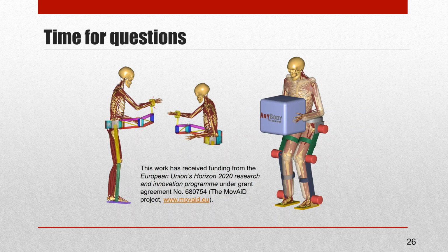Okay, thanks. So let's go to the next question. How do we calculate the total metabolic power? The current versions of AnyBody have an opportunity to calculate the metabolism of every muscle. Whenever you do an analysis, you can browse your way into the muscle, and you can get information about the metabolic power of the muscle at any time instant in the analysis. New versions that are coming out of AnyBody have a much improved metabolism model that we implemented recently, but it still works the same way. If you want the total metabolic power for the entire body, all you have to do is simply sum up all of the muscle metabolisms, and then you get the number for the entire body.